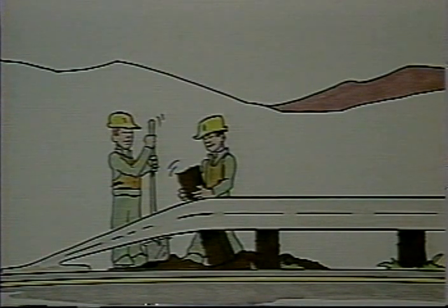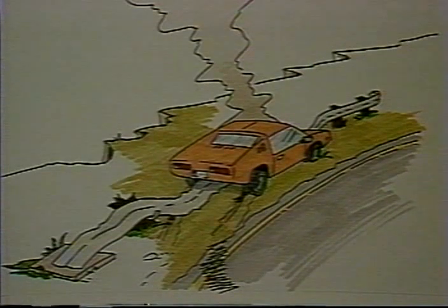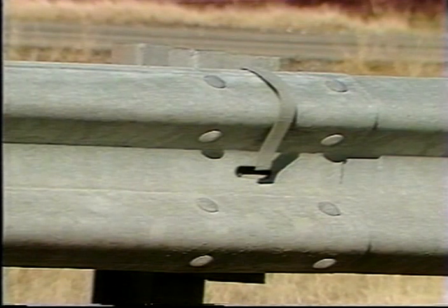Basically, what has been done to correct the problem involves removal of a post and rigging the railing so that it can fall down when impacted. This is called CRT, or Controlled Release Terminal. One variation is the clip and short section of W-beam. Other variations perform in the same manner. Fundamental to the system's working as designed is the requirement that the rail release from the supporting posts as soon as the end treatment is loaded with a downward force. Various rail post connections are used.